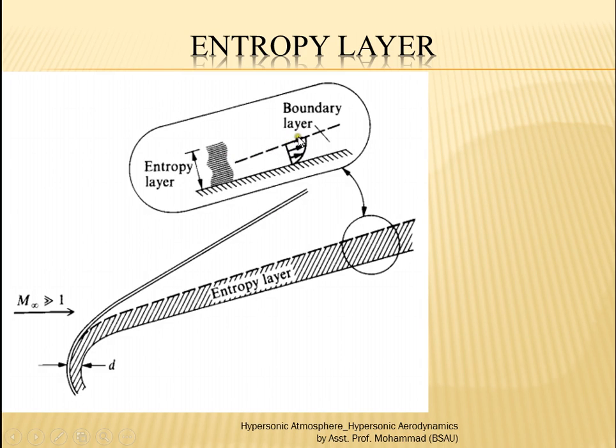What is the normal condition here? We assume that in this region the flow properties change, especially the velocity, but at this region whatever flow properties are available in the free stream, the same flow properties will be available here. So we are sure now that at the end of the boundary layer, or boundary layer edge, at the boundary layer thickness, at this edge we have similar properties to what is available in the free stream flow.